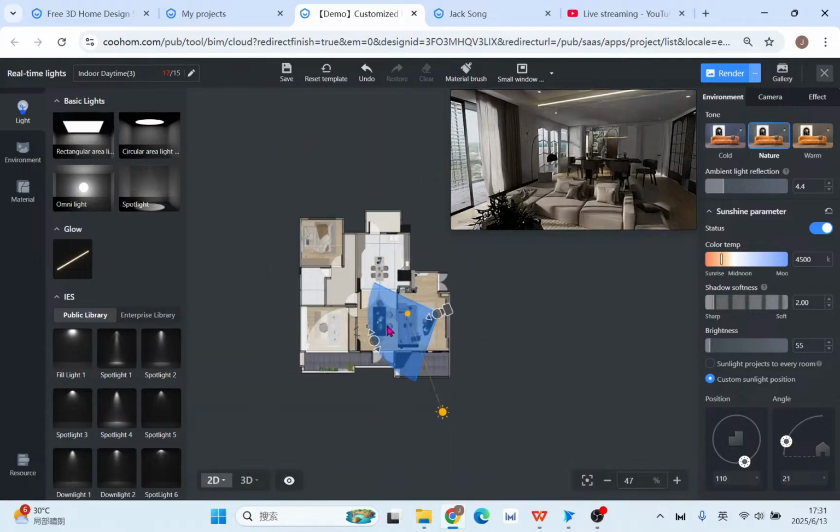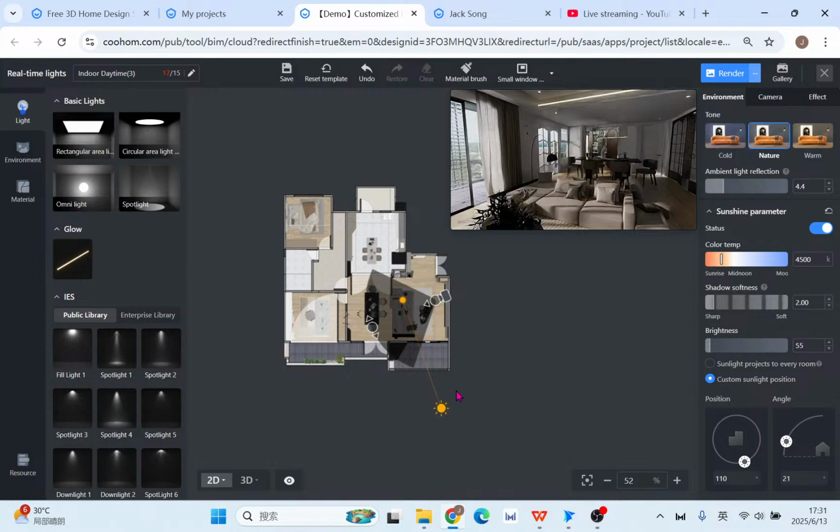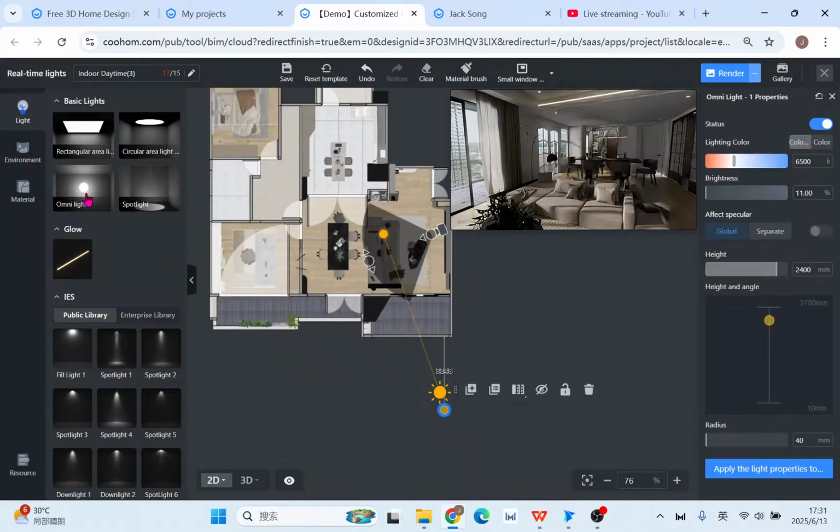And then the second thing, we need to have the outside ambient light, the environment light. So how can we do that? Use the ambient light. It's easy. This is for the simulation of the light bulb, but we still need to make it stronger. Put one just next to the sun. This time the color temperature is 8,000 to 10,000 Kelvin. Make it feel like the outside blue sky and white clouds.